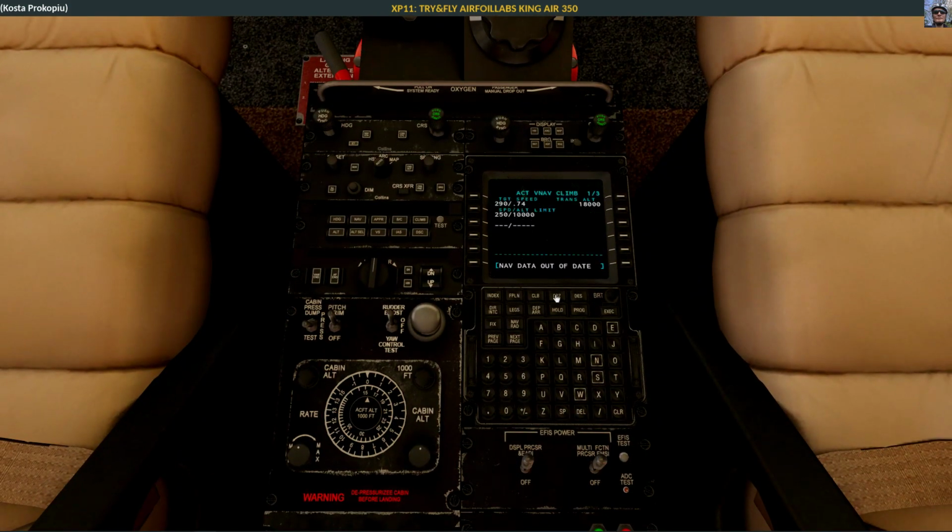It appears to be almost okay. The climb speed, that it did not remember, but that's how it goes. So we'll put that here, then we put the 5000. Then for the cruise, it's okay, but it's a little bit fast. So I put this on 250. And for the descent, again, oops, we need the transition, and I think I